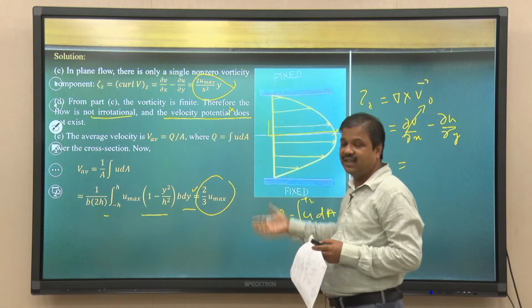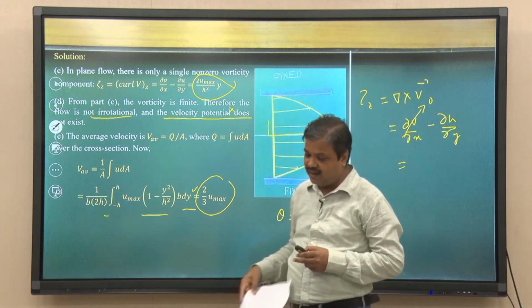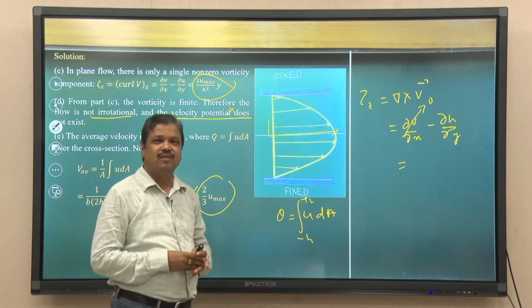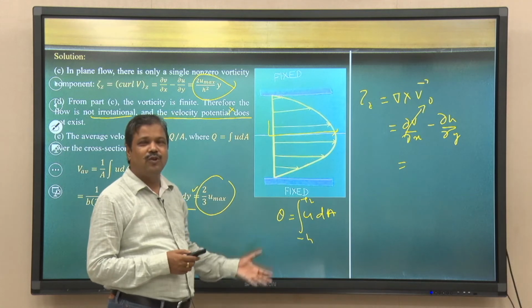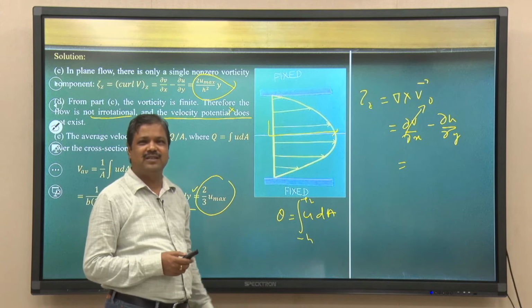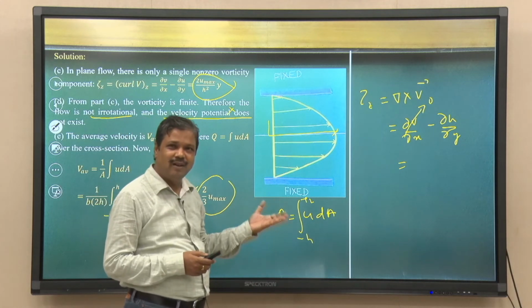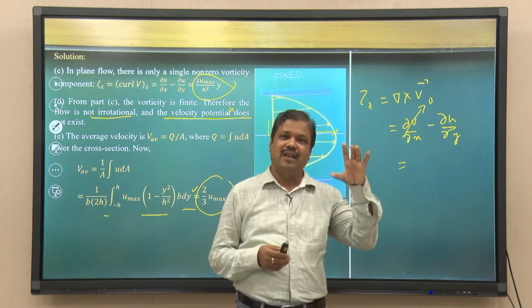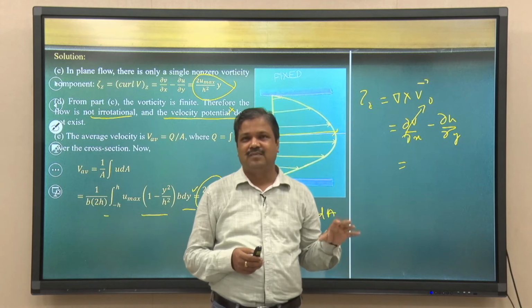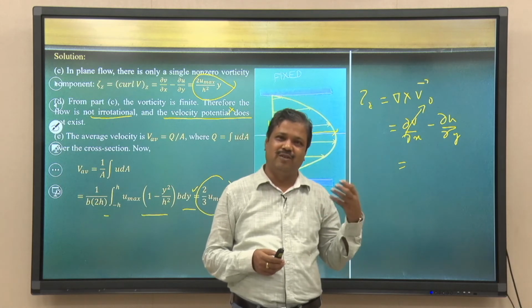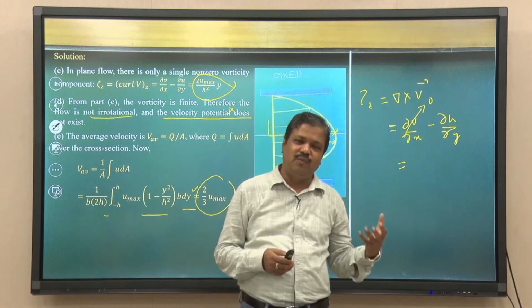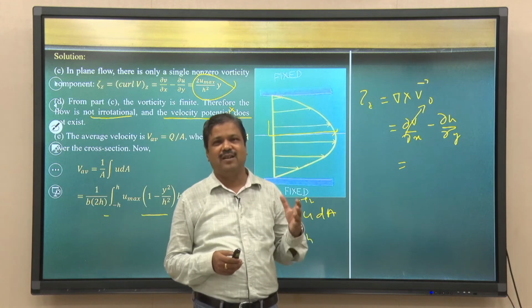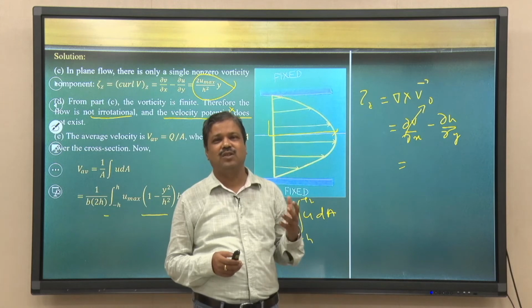So, that is an example here, as compared to the integral approach where we simplified many things. In the differential approach we need to do the integrations and differentiations to get the pressure field, the wall shear stress, the stream functions, the velocity potential function, with a lot of approximations: two-dimensional flow, incompressible, Newtonian fluid. So, I am repeating to tell you that fluid flow problems are not easy; you simplify them for specific cases to get some solutions.